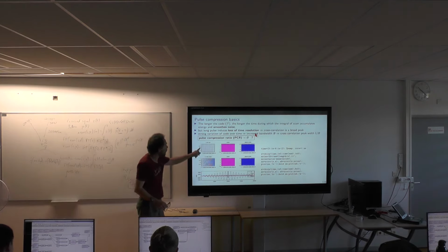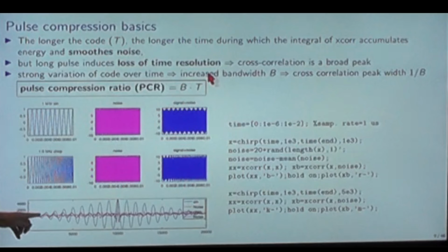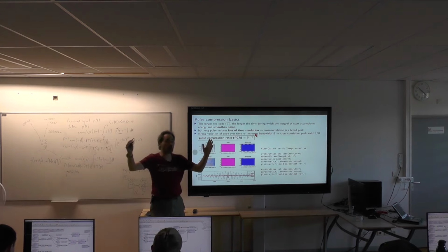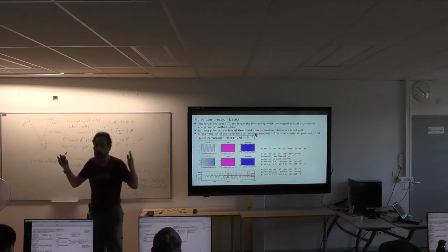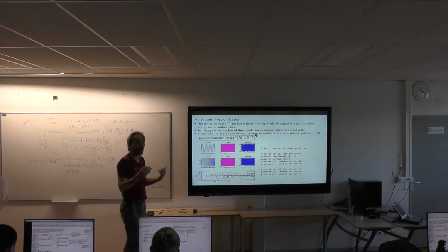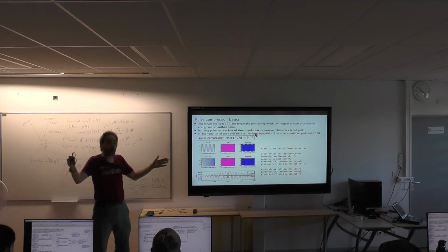So here you have a sine wave, and the sine wave is polluted with noise, and you say, let's average out the noise, so let's run a sliding average. And you get the blue curve over here. So yes, the blue curve, you see that you managed to extract the sine wave and get rid of the noise. But by doing this, you actually spread the information over a longer duration. The longer the sliding average duration, the better your noise cancellation capability, 1 over square root of n, with n the samples over which you average. But by doing this, you've spread the information.